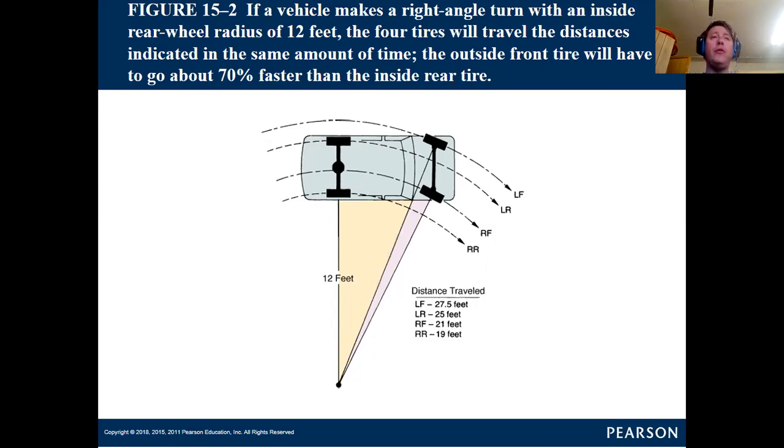That vehicle is driving in two-wheel drive, and the four-wheel drive option is simply for slick road conditions or off-road conditions where you're going to have a friction surface between the tire and whatever it is you're driving on that's slick enough that the tires, while locked in four-wheel drive, the front axle and rear axle can spin at slightly different speeds, and the operator of the vehicle won't notice it. No damage will be done to the vehicle because the slip is allowed to take place underneath the tires. Excuse me.